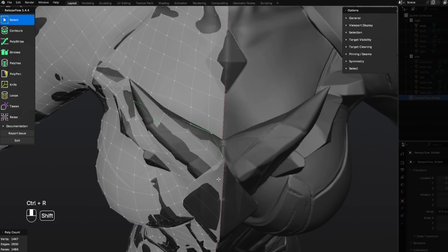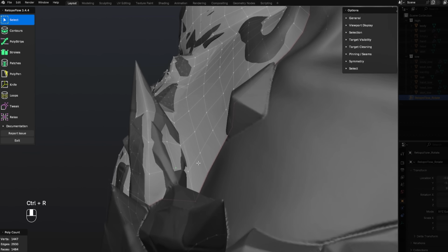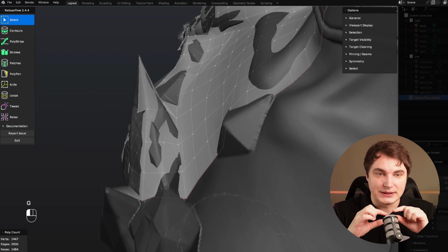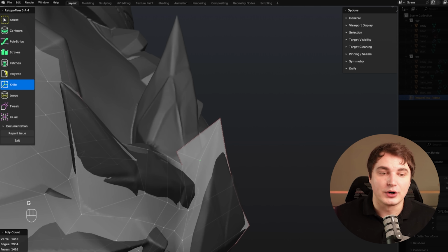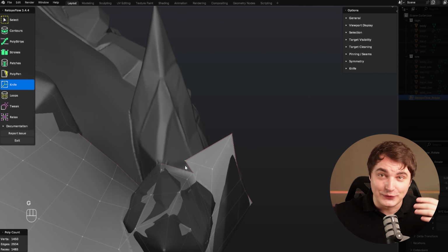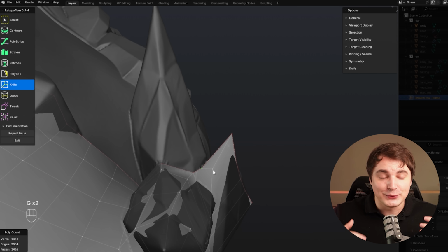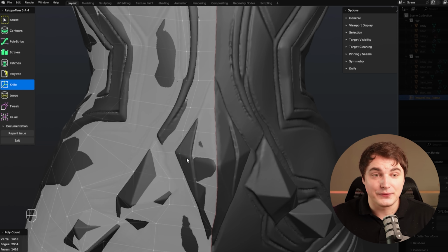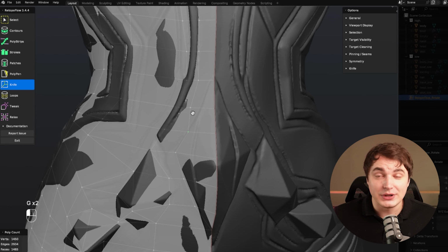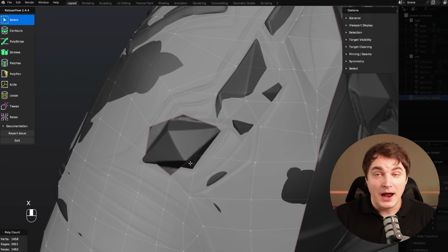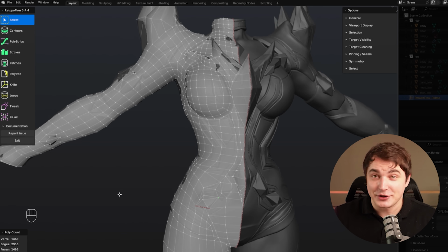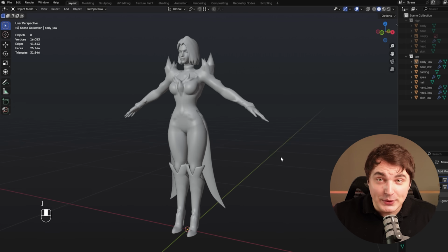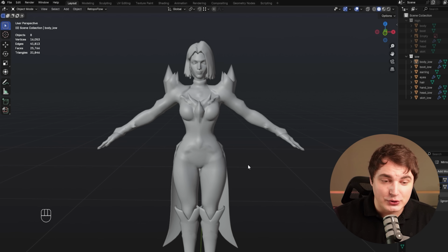So what I'm gonna do, I'm gonna go through the mesh and see where it's not dense enough or maybe where there are holes or problems. Also, the reason why I'm not skipping this part is because I want to do a baking of normal map and ambient occlusion map that will add a really nice look on top. For some simple objects, you most likely gonna skip it. But for some big ones, especially if you intend to do baking, I recommend this workflow. I tested a lot, guys. This one is the fastest, guaranteed. Okay, and after 5 minutes in RetopoFlow, we fixed almost all the issues.